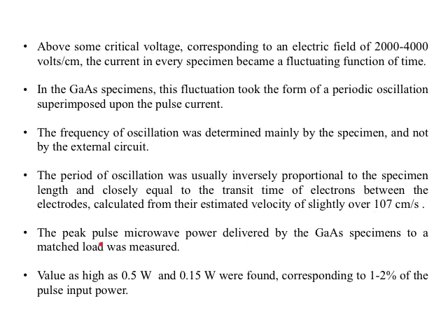The peak pulse microwave power delivered by this gallium arsenide specimen to a matched load was also measured. Values as high as 0.5 watt and 0.15 watt were found, corresponding to 1 to 2% of the pulse input power.